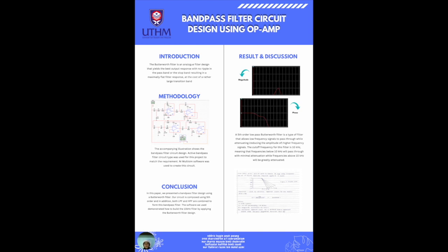The frequency response of the Butterworth filter has no ripples in the passband and rolls off toward zero in the stopband. Butterworth filters have a monotonically changing magnitude function with omega, unlike other filter types that have non-monotonic ripples in the passband or the stopband. Monotonically means that the signal does not progressively increase or decrease.